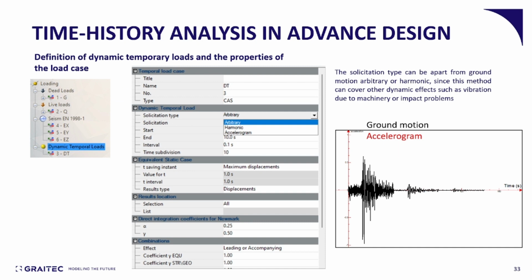So, time history analysis in advanced design. Advanced design has the option to set up a time history analysis and solve it with the direct integration. The only thing the user needs to do is to set up the dynamic temporal loads. And we have different solicitation types the user can define.